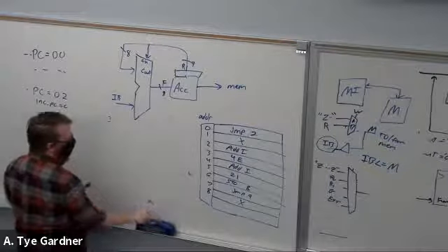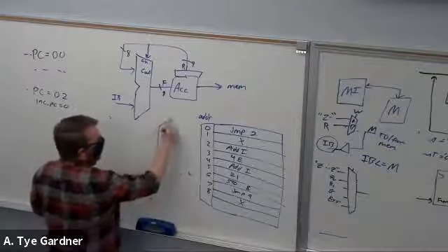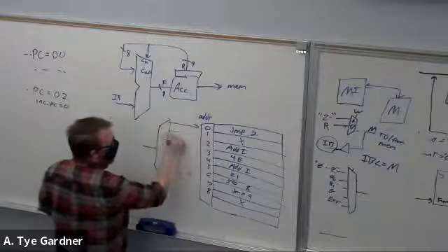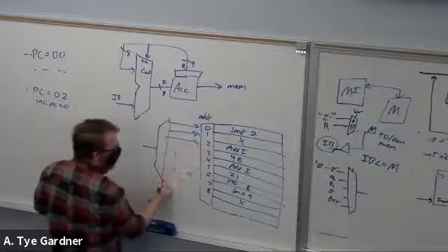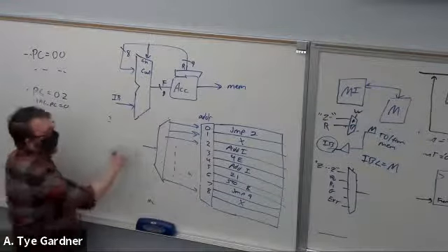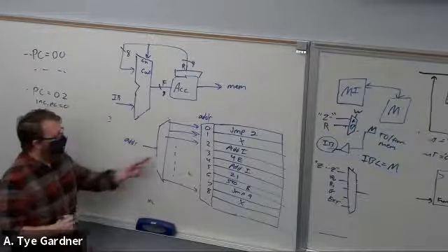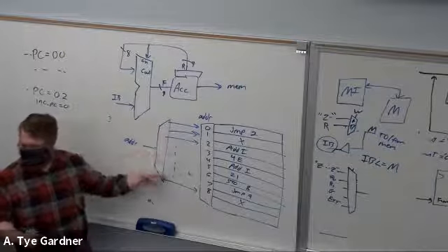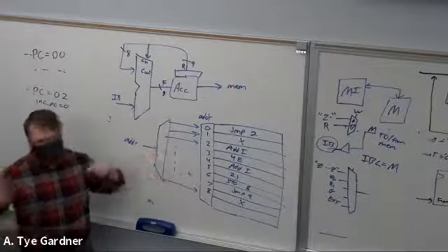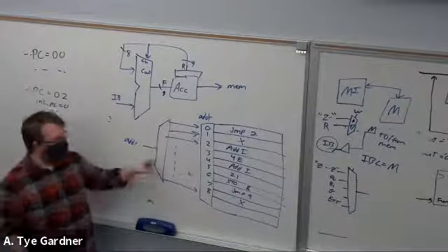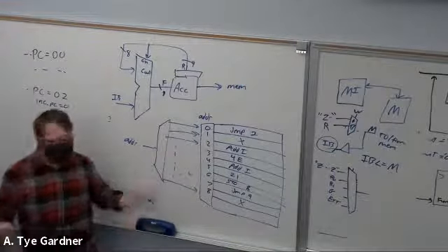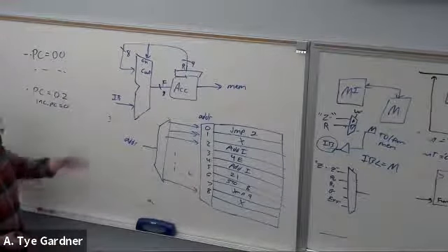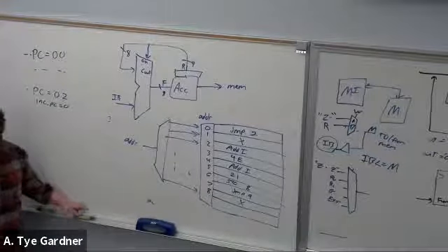It's addressed at the simplest level by a decoder that just takes an address, right? And a decoder's whole job is it is given an address and asserts exactly one of these outputs. And when that address is asserted, remember that AND gate diagram that I drew, it sends those bits out and you have now access based on its decoder. That's all it's doing. This is why it's important. Okay.